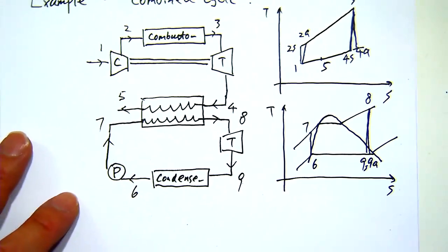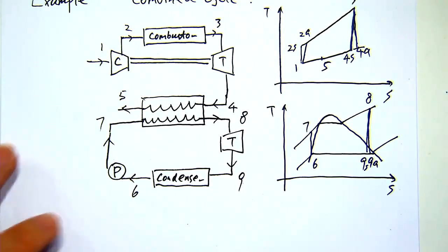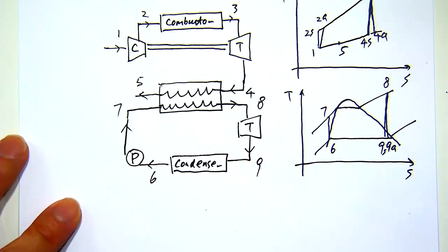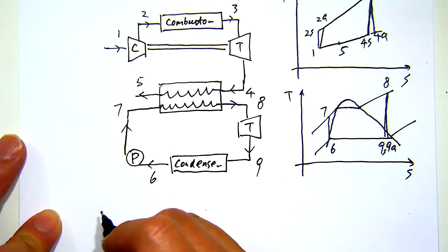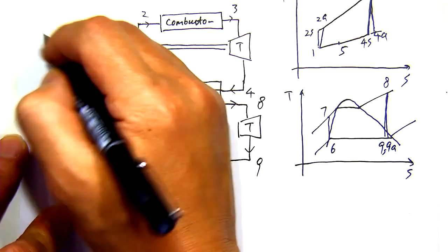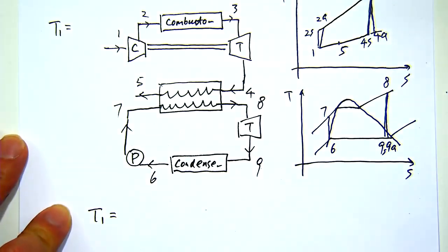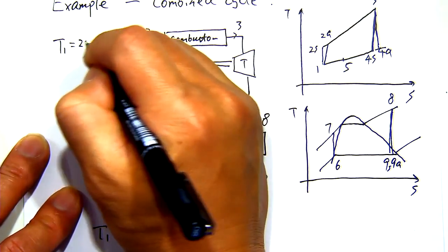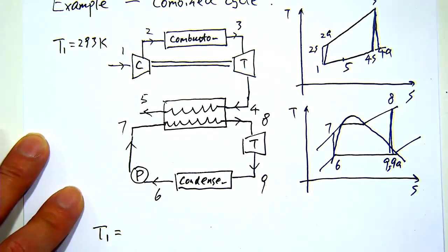All right, so that's the step. Let's basically set up the problem. And let's put down the knowns or given conditions there as well. So what is given is T1 equals 20 degrees C. I directly convert it to Kelvin because the calculation I use could involve the isentropic law or the ideal gas law.